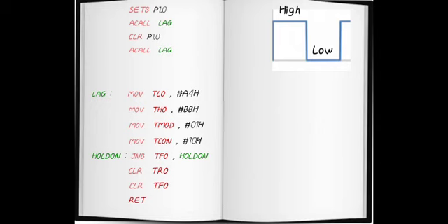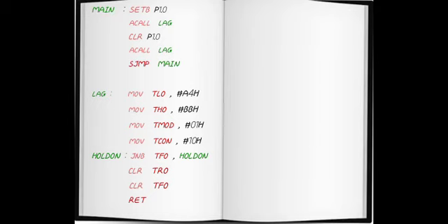To get a pulse train we have to add a jump instruction, SJMP, which would infinitely execute these codes, and a continuous pulse train would be generated at pin P1.0. So this is all about the program to generate a square wave of time period 35 millisecond.